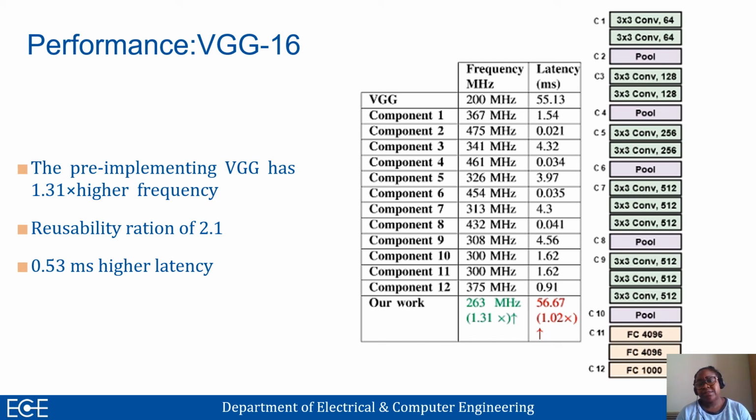When several design components must be spread around the chip, a rising issue is how to deal with fabric discontinuity such as erratic tile patterns and I/O columns. This discontinuity increases the data path and has a negative effect on the performance. In order to tackle that issue, the tool inserts pipeline elements such as flip-flops on the critical path in order to improve the timing performance, but this has a side effect on the latency, which increases.